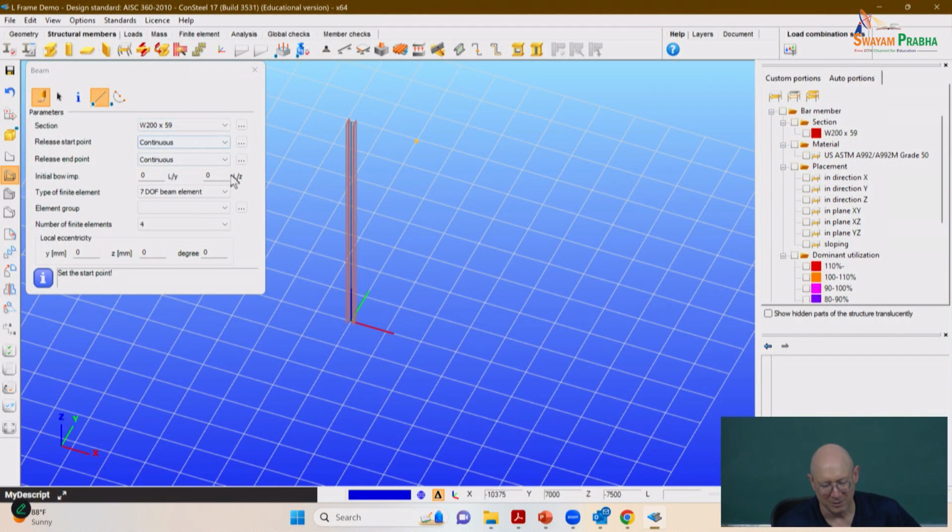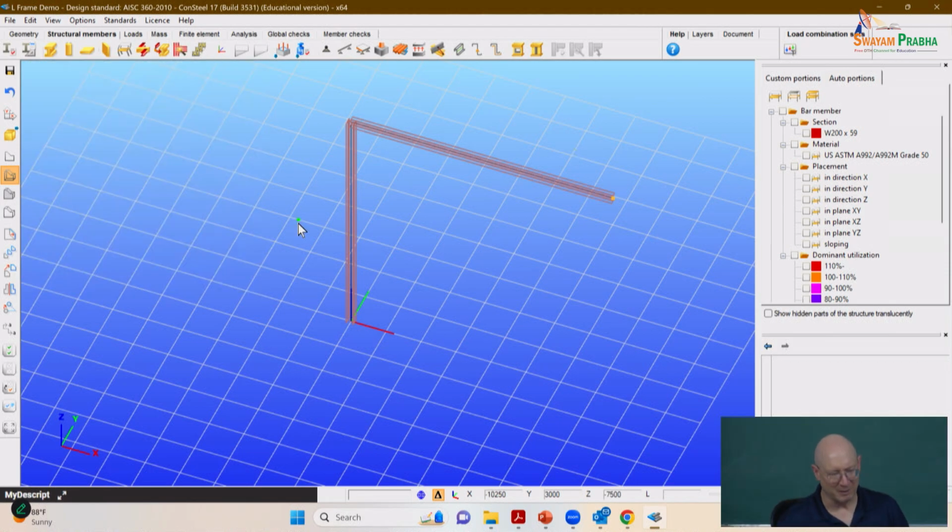So if I come here, I select the top of the column, I drag my mouse button out, let go of the mouse. If you've got your hand on your mouse, it'll screw up your X, Y, Z. X, 7500, Y, 0, Z, oops, X, 7500, I hit X accidentally, Z, 0. Return. Okay? All right, so we got our beam and our column. Never defined any nodes.